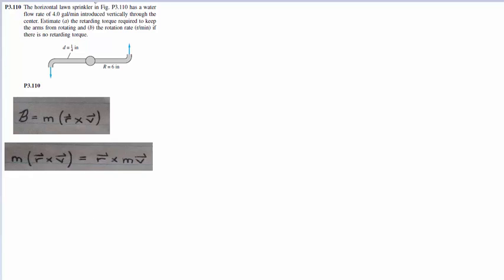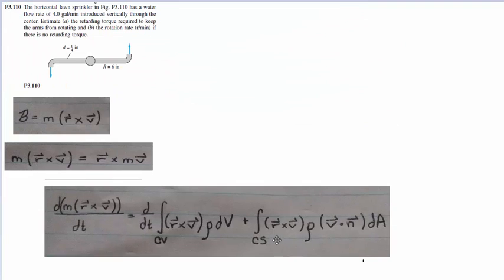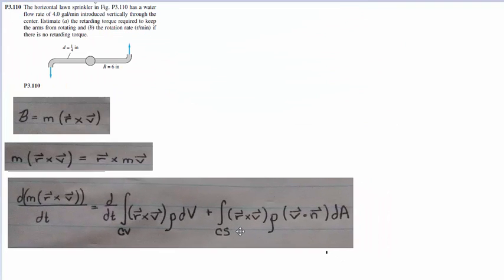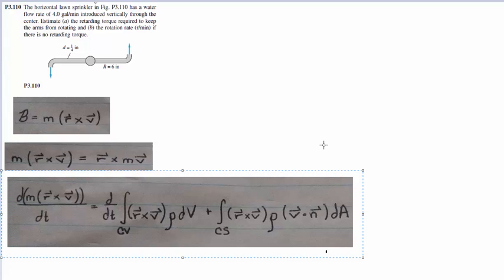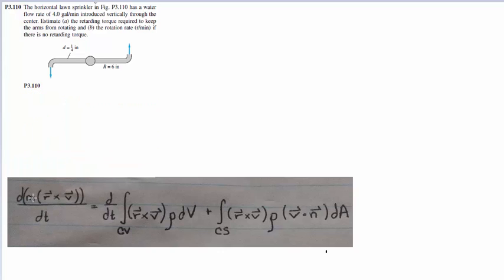So we're going to take this beta value, and we're going to put this beta value into our general form of the Reynolds transport theorem, and that's going to look something like this, which probably looks a little bit scary right now. Try not to freak out too much about the math. It looks pretty similar to what we've seen before. So here you just have this d beta dt term right over here. That we just subbed directly in our angular momentum.